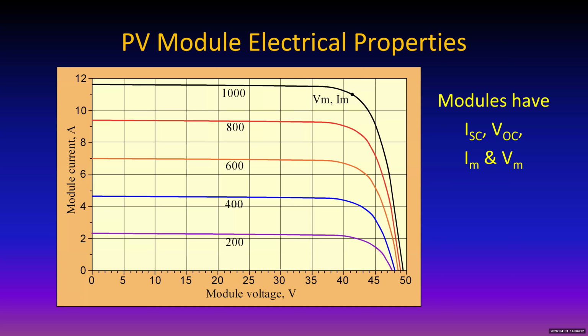If you short the two module leads together, the module won't blow up. It'll simply have a certain amount of current going through it, and the voltage times the current delivers 0 power, which isn't quite true because it's not totally uniform and there will be some power dissipated in the module, but it does not damage the module if you short it out.